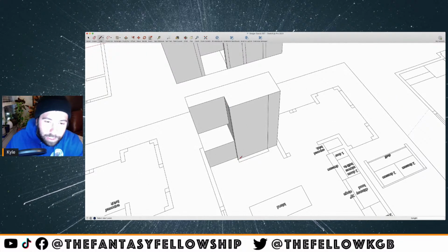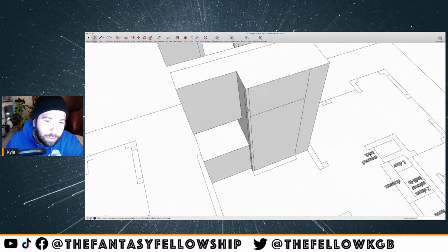It looks like she gave me a 31.5 inch gap for this fridge. So a 36-inch fridge, that's a typical size. I'm just going to go 1.5 inches in. Typical fridge height, usually around 6 feet. And then she did leave me 1.5 inches for a panel here on the end of the fridge.